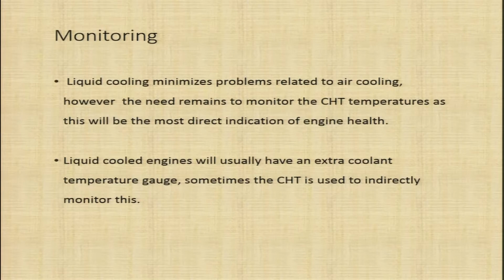Monitoring. Liquid cooling minimizes problems related to air cooling. However, the need remains to monitor the CHT temperatures, as this will be the most direct indication of engine health. We have seen what air cooling is and what liquid cooling is, and liquid cooling minimizes a lot of problems that air cooling had, but still we need to monitor the cylinder head temperatures of the cylinders, as this will be the direct indication of our engine health.